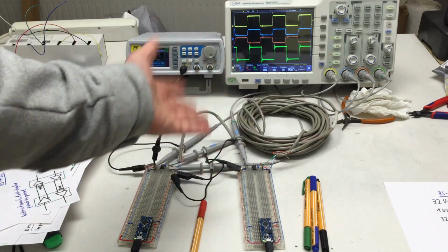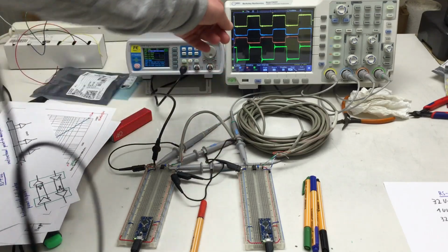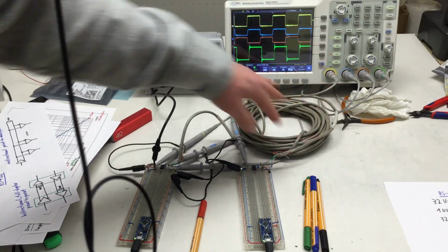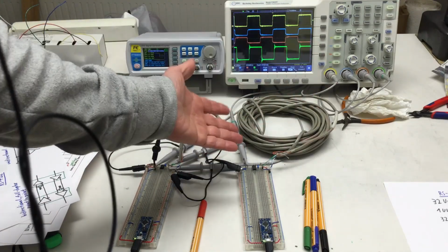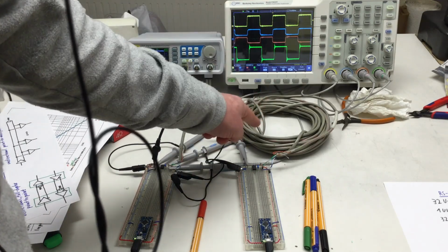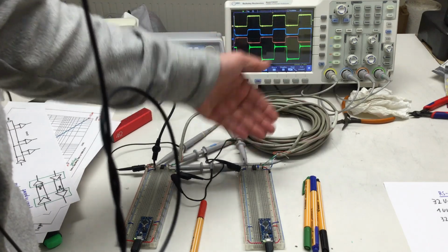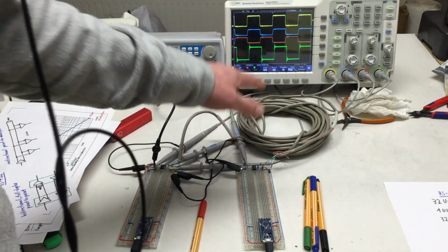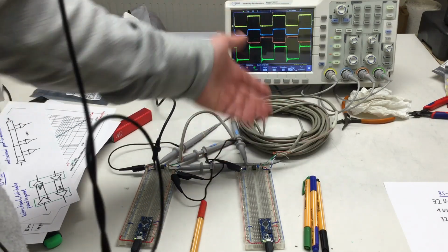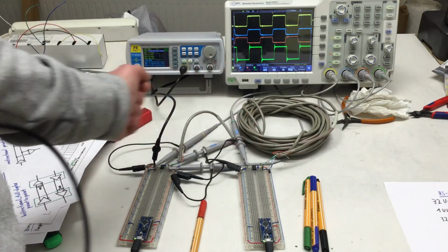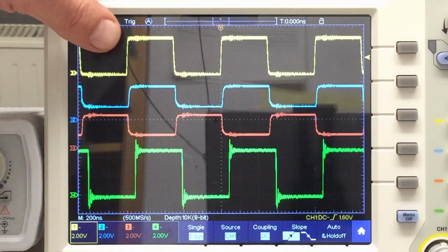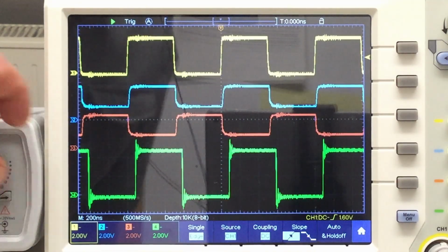And now let's see if I can indeed transmit a 10 megahertz square wave over that 10 meter of Cat3 twisted pair cable via RS-485. Little caveat here, this is an Ethernet Cat3 cable and it has an impedance of 100 ohm. A real RS-485 cable would have an impedance of 120 ohms. Those we also terminate at both ends with 120 ohm resistors. But anyway, let's try. We're still at the 1 megahertz we started the video with, so let's turn that up